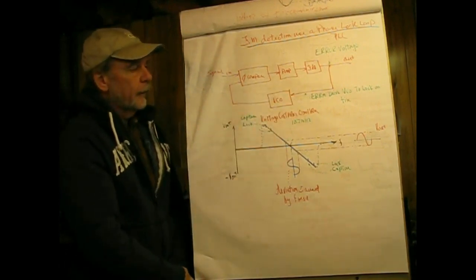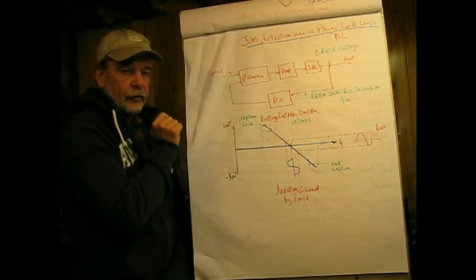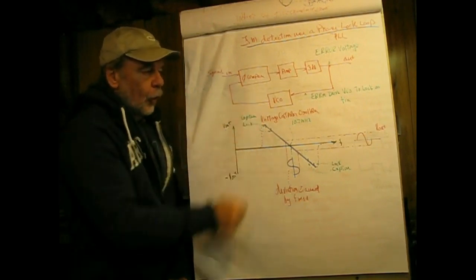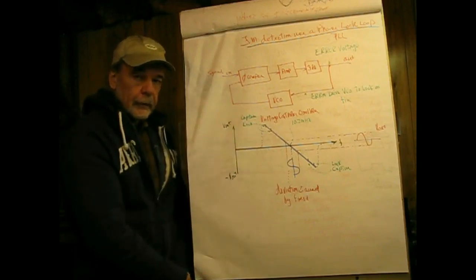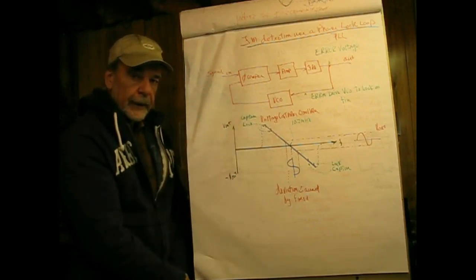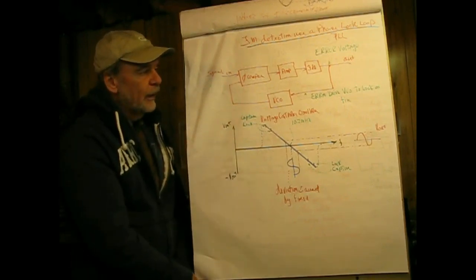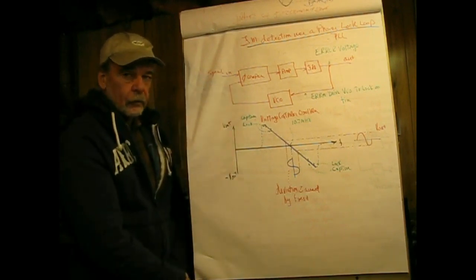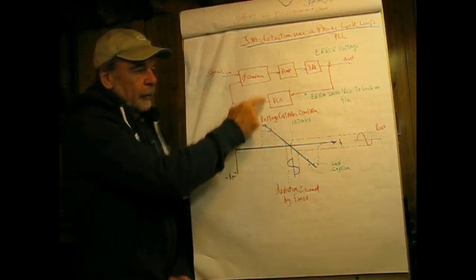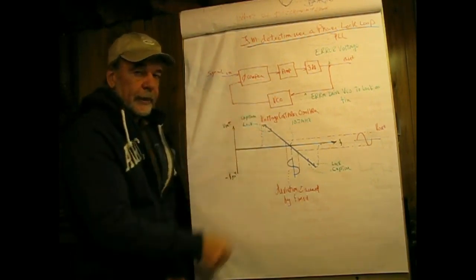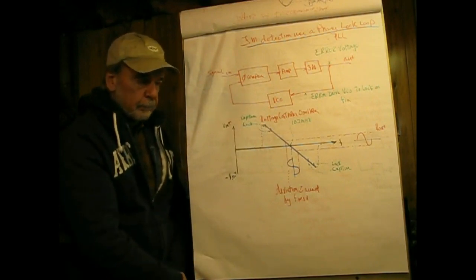Now, the interesting thing is when you apply the signal, the VCO doesn't necessarily immediately move toward the frequency of the signal. Sometimes it moves away and comes back. It's a complicated relationship when the signal's applied, but ultimately what we want is lock. Lock means that the phase output's going to be a little bit different, but the frequency is going to be exactly the same.